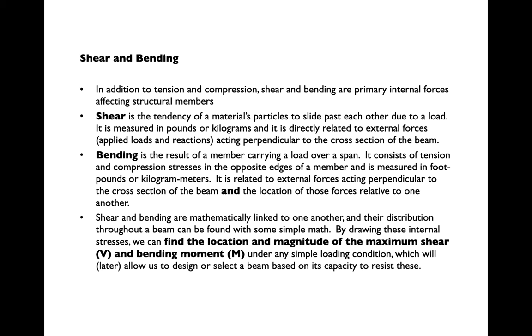Related to this, but a little bit more complex, is bending. Bending also results from putting a load onto a beam perpendicular to its longitudinal axis. Bending is actually a pair of forces. It is tension and compression in the opposite edges of a member. And we measure this the same way that we measure moment. We measure it in foot-pounds or kilogram meters. It's related to the external forces, but as we'll see, it is also related to where those forces occur on